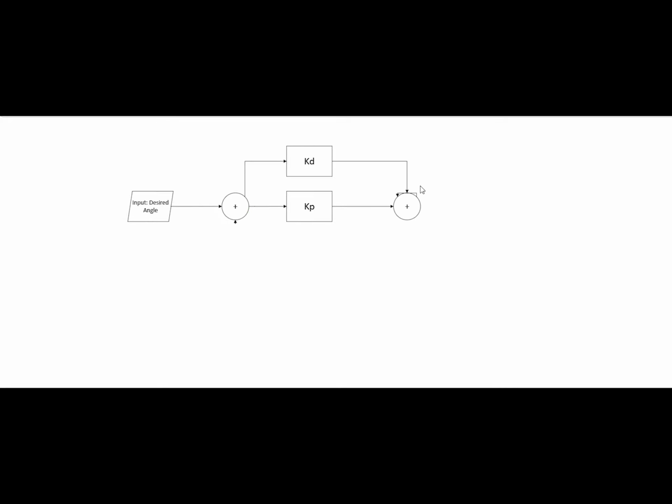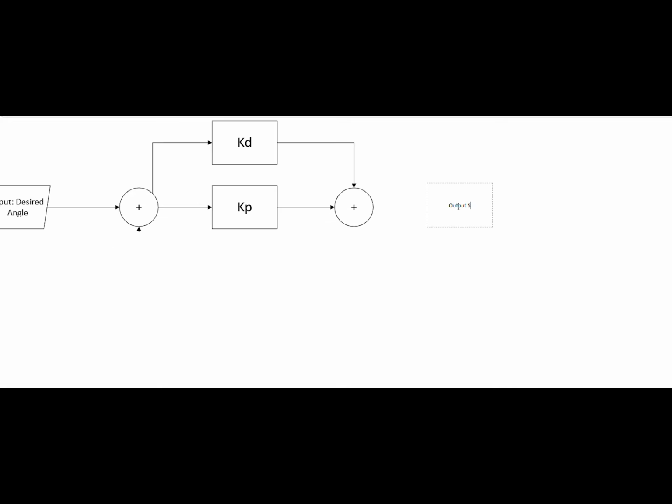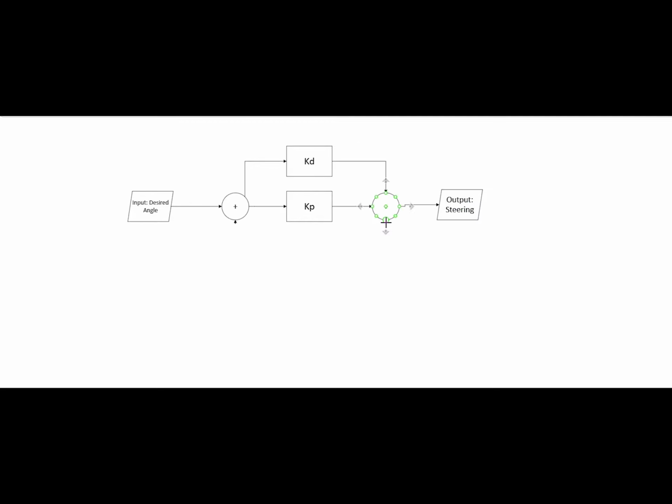Finally, our team developed a PD controller based off of this angle calculation. Given that the desired angle to follow the road is 0 degrees between where the robot looks and the center of the road, the angle reading is used as the input error. This means that based off of whatever angle the robot detects, it will adjust its steering based off of both the derivative of its angle and the current angle proportional to whatever reading it receives.